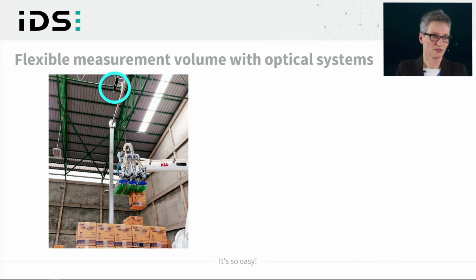That's true. The robot doesn't need 3D data to stack boxes here, but you want to check if the calculated place for the next box is currently free. So maybe some box fell or was misaligned, and then you are not able to put a new box in this place. So you check the free space before moving a box to this position.